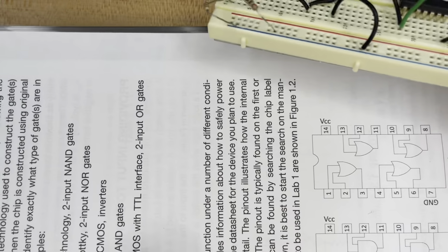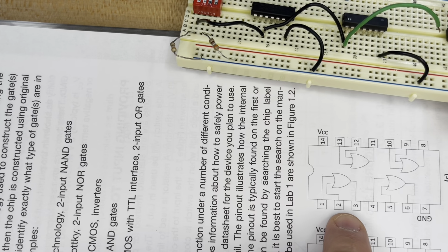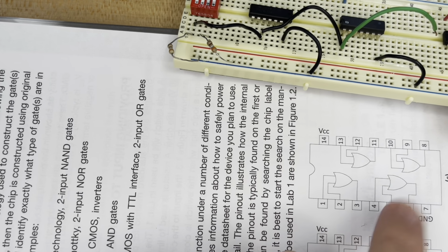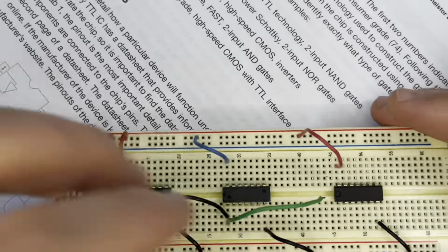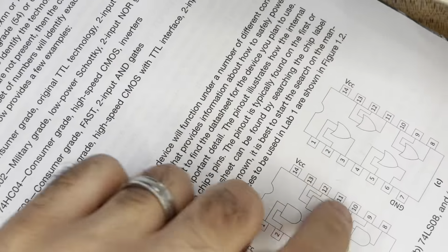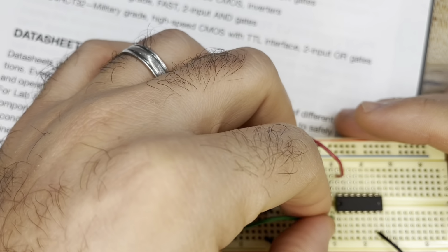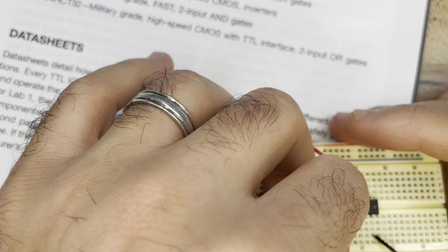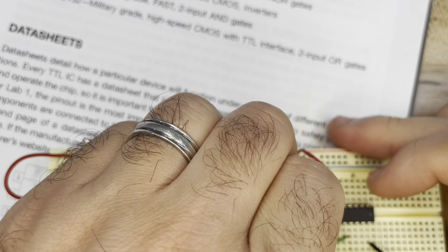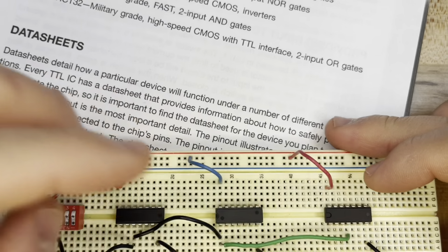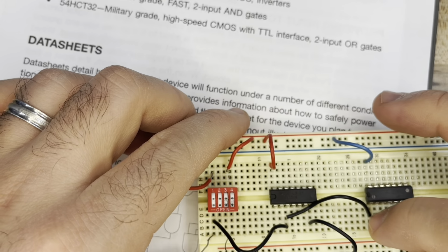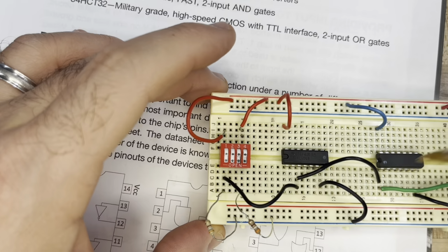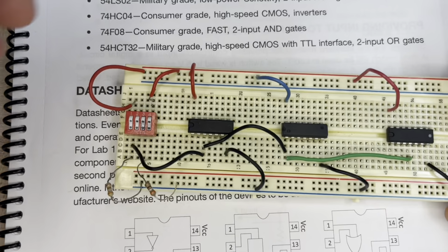Here we go. And last, I'm gonna take it from the same point to the third gate we're gonna use, and for example, let's use the second OR gate. So pin number 4 and pin number 5 is the inputs. So this one needs to go to pin number 4. Here we go. This is pin number 4. So now I have all of X, X, X, X, and X. Okay, now we need Y.